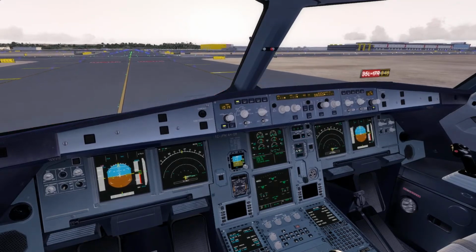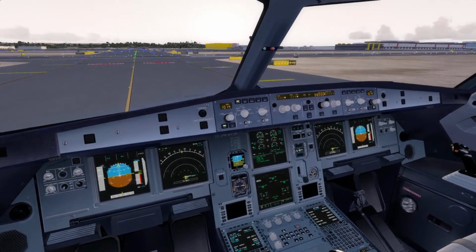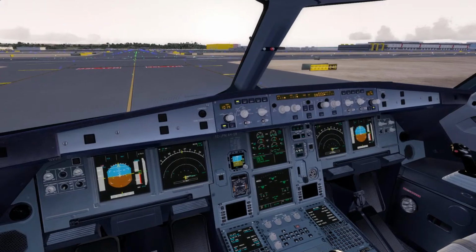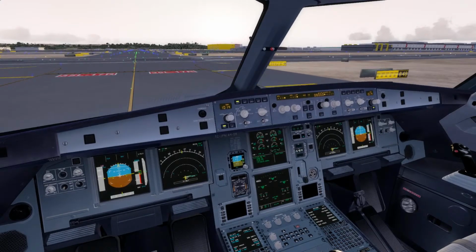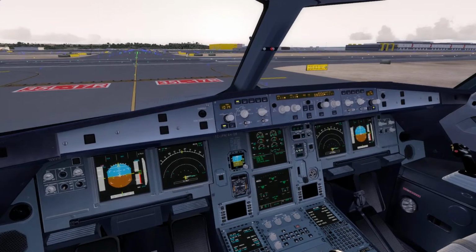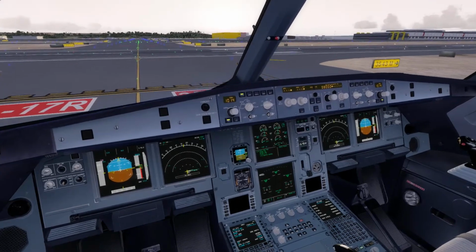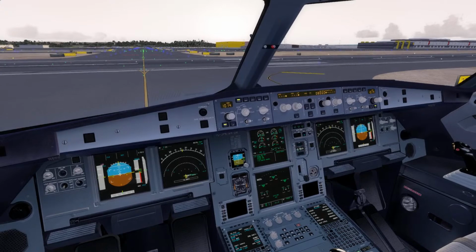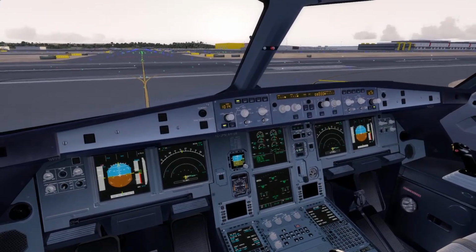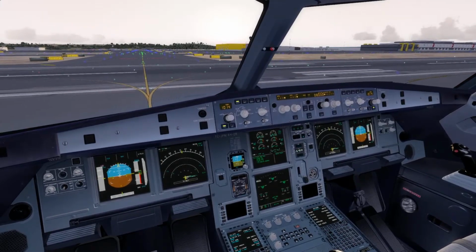I've set the proximity warning system, and the Turkish 79 Alpha Victor, surface wind 060 degrees 11 knots, runway 35 left, clear for takeoff. Clear takeoff, runway 35 left, Turkish 79 Alpha Victor. And here we got a clearance, and we have also completed the before takeoff checklist.